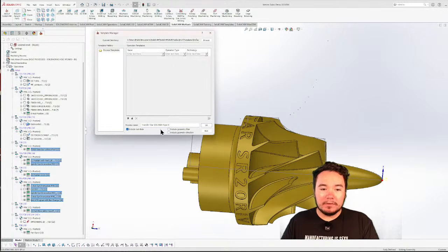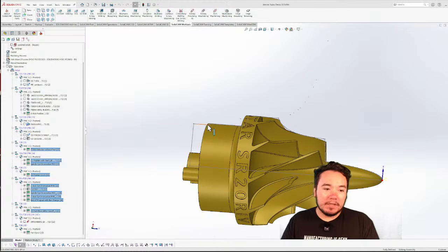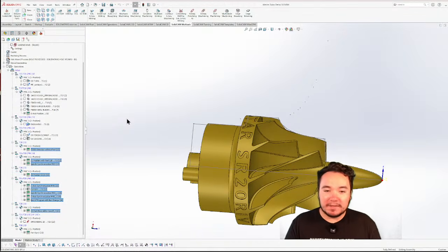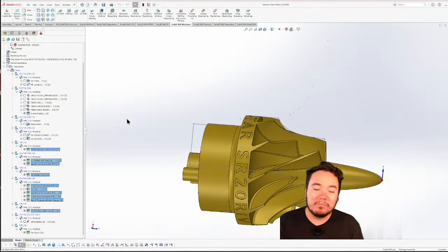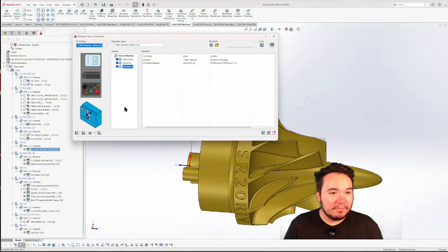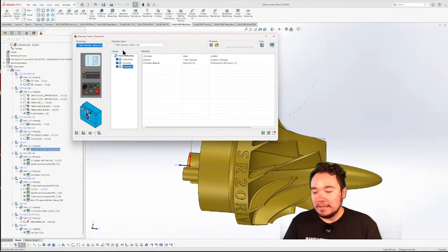And then you can do include tool data, include geometry filter if you're using the same tool for the cutoff, and you can hit OK. And that'll save it, and then you can drag and drop it onto whatever part you're doing. You're going to have to adjust just a few things, and I'll show you which parameters you are going to have to adjust. But from there, T2000 selection, that's going to home the sub-spindle in line with the main. So we're ready to do our pickup.